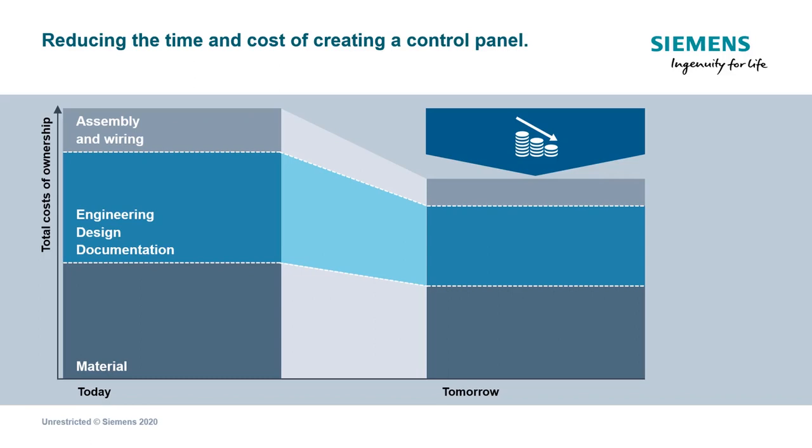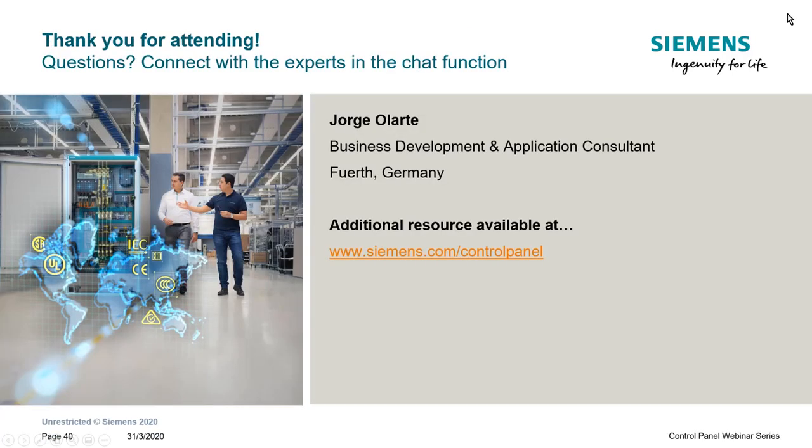Customers often may think, well, I need a 50 kiloamp control panel. Remember, talk to them. Usually a lower breaking capacity is actually needed. And this you can achieve using the SIMARIS Design tool and understanding why the short circuit changes this. Also, depending on the markets, you will find it easier to use fuses or unfused designs. This is also something that you have to speak with your customer about.